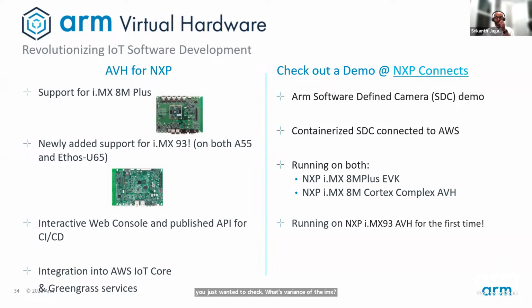Yeah, so we have the full-featured 9352. That's the 11x11 package with the NPU enabled along with two A55 cores. And it's industrial qualified. So 9352C is the SoC variant that we have on the evaluation kit.